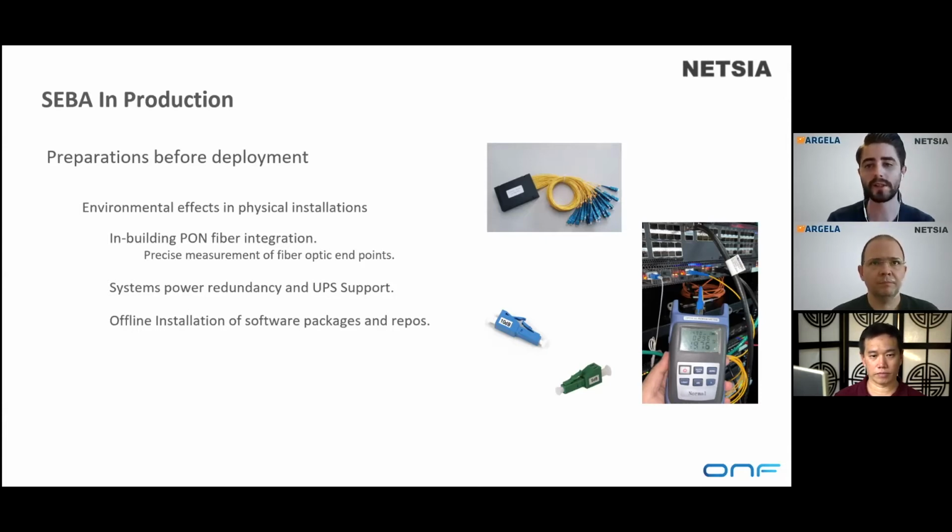In this sense, we made precise measurements for the wiring of the devices we placed in the subscriber houses. To adjust the correct power level, it is necessary to use signal attenuators when necessary. In indoor installation, we use 5 dB and 10 dB signal attenuators in places.